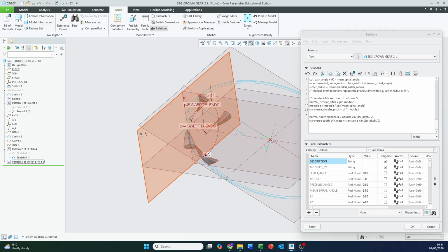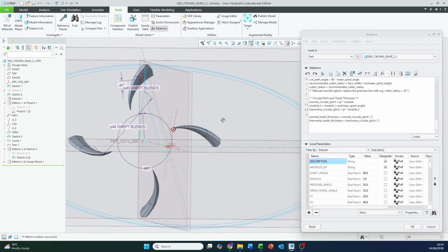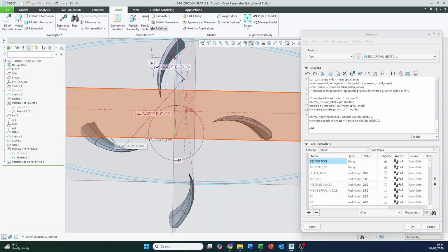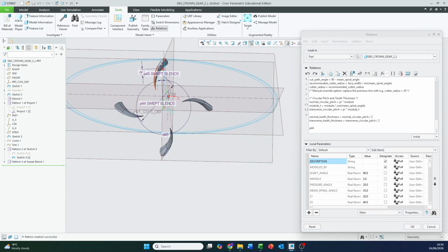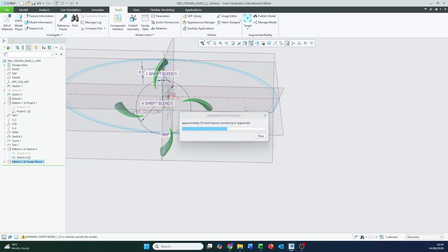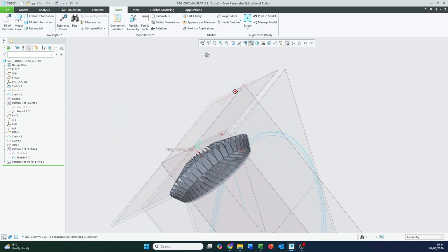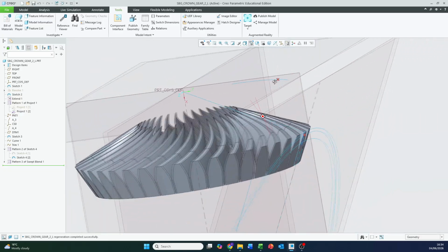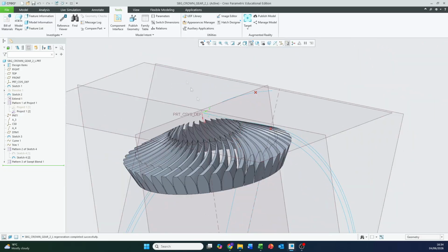Click on the pattern within the model tree, select the correct pattern, which is the one, again, that's connected by these lines between the first two components of the pattern, and equals Z2. Press OK, Control G, and just like that, we have the teeth of Gear 2.